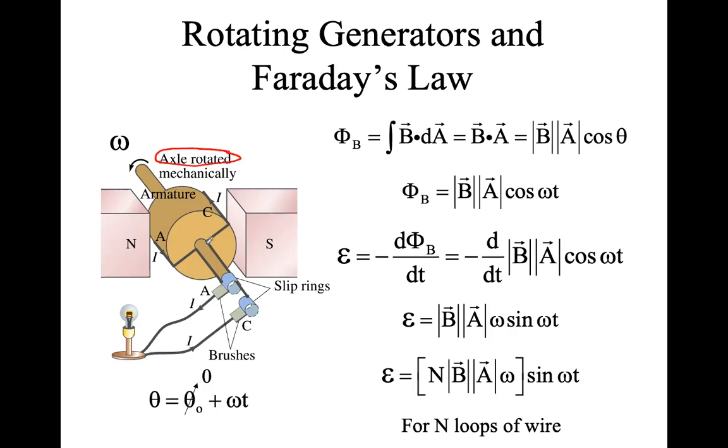And you put a loop of wire. We've just shown one here. Obviously, it's many, many, many loops in a series configuration around there. And then at the very end here, you get the power out that you need, okay? And so what happens, I guess, same steps we talked about before. What area do we have? And it's right there, right? I'm looking at this loop, and you can't see the backside, but it's sitting there in between the poles of a permanent magnet. And so the flux must just be B times A.